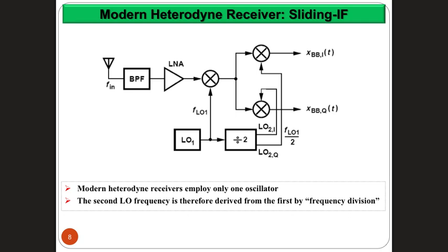Does that mean that we cannot have a variation in the input frequency? Yes, we can have a variation in the input frequency, but if we have an input frequency that's different from the one we calculated for LO, you have the band pass filters, and you will have a variation of the IF stage, not the input frequency. Input frequency can be anything. You multiply it by a local oscillator value, it will bring you to IF. The second one, that IF has to be brought down to 0. Okay?